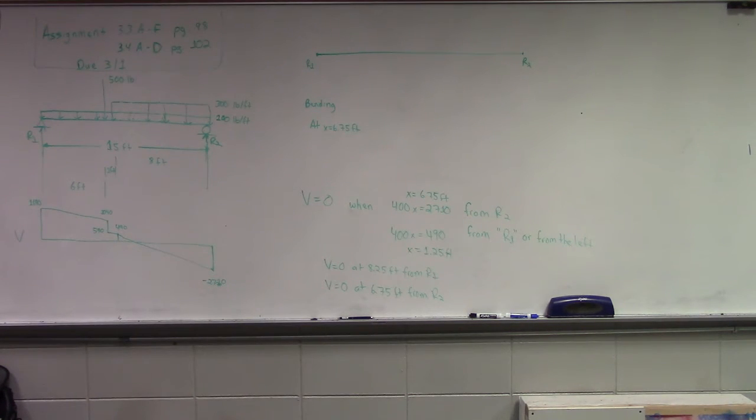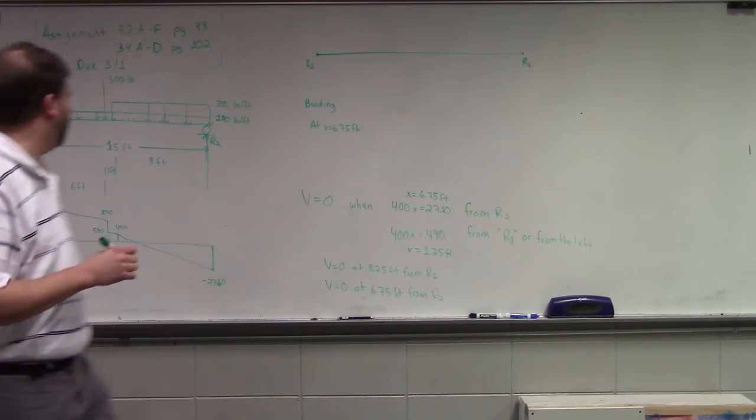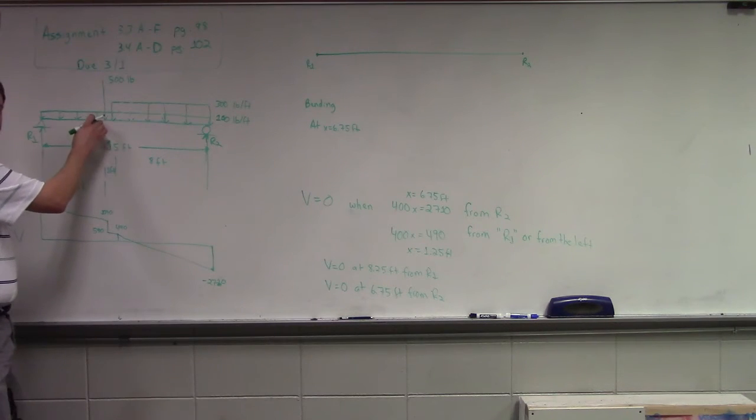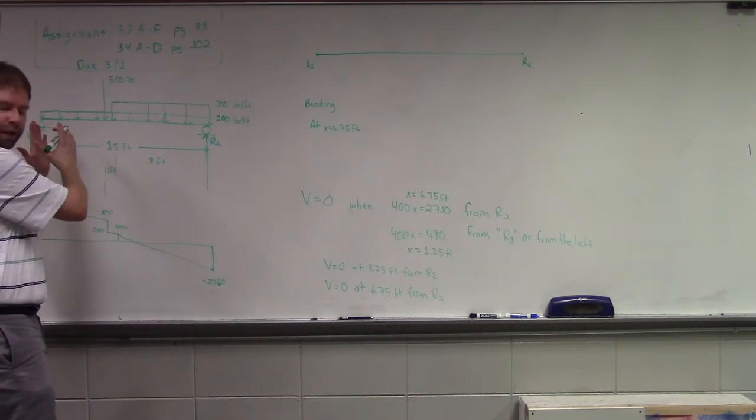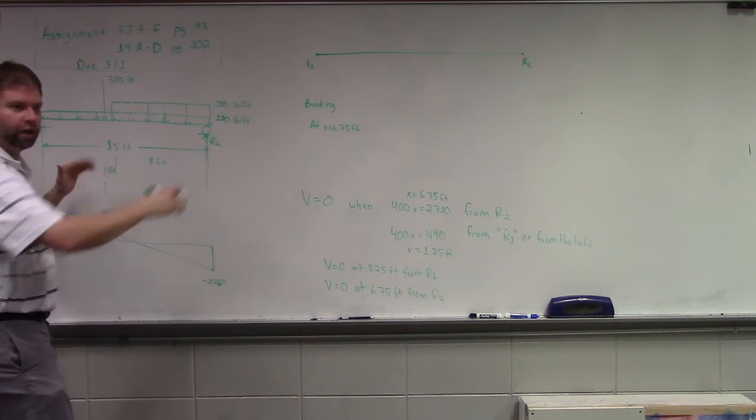And what is the process? Do we remember what the process is for determining bending? What's different about bending than about shear? You have to pass the point load. Yes, remember in shear, we have to look at the left and the right-hand side of our point loads. We don't have to do that in bending. We just march along, okay?